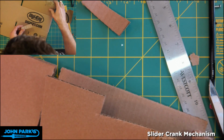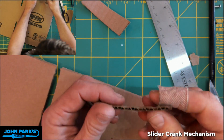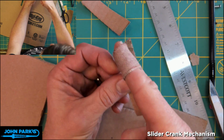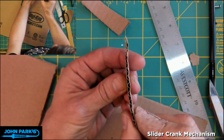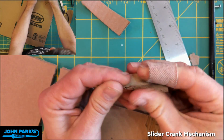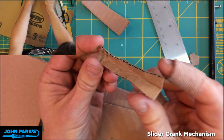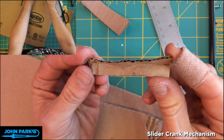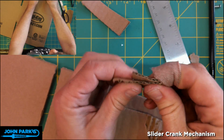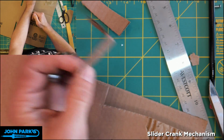You will also find, so I mentioned grain. We'll talk about that more, but you'll see that it's quite rigid along this axis, which is against the grain. So it doesn't really want to bend nicely. You'll see I'll have a hard time making a crease there. I make a big mess trying to go against the grain, whereas with the grain, just like with wood, there are advantages and disadvantages to going in those two directions.